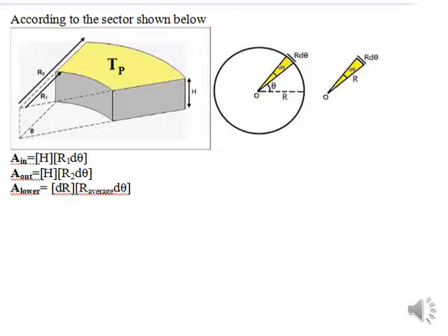While if you look downward or upward, where the heat is crossing that nearly rectangular area, we can see that its length is a curved path whose length is r average d theta. That's the average arc length passing through the middle of the rectangle, and of course your width is dr. So it is again area upper, equal to r average d theta times dr.